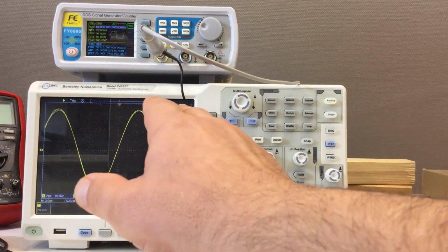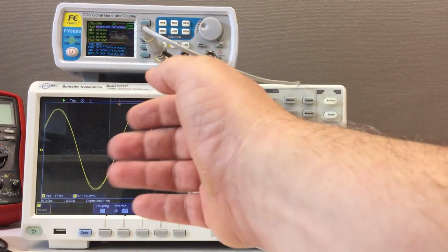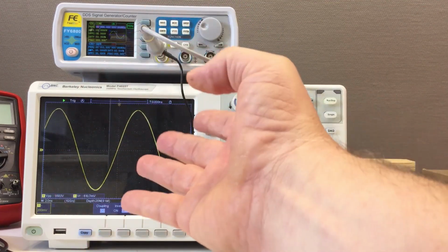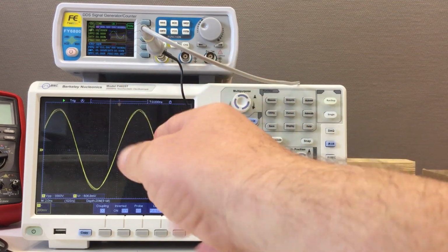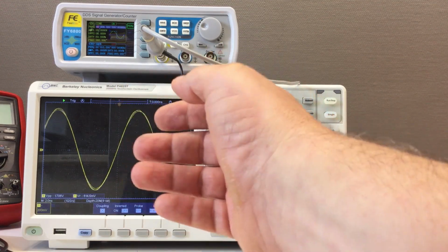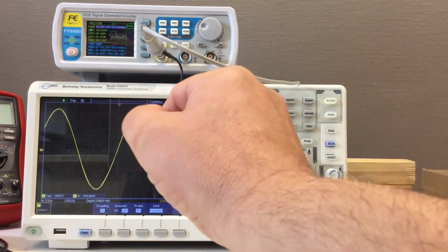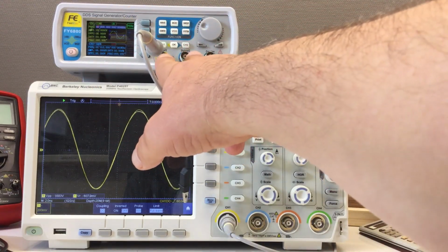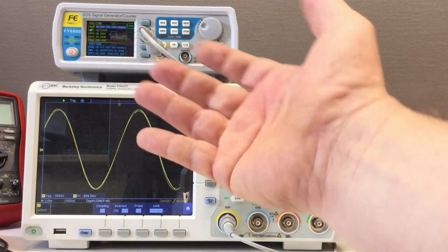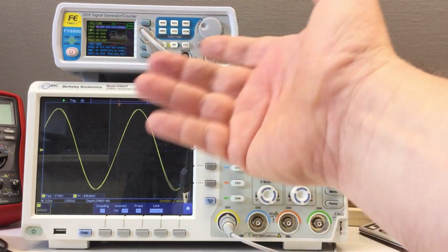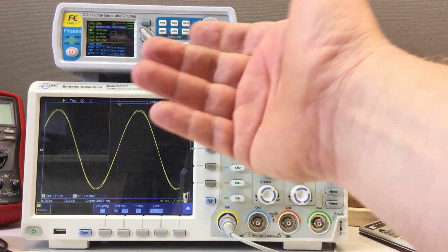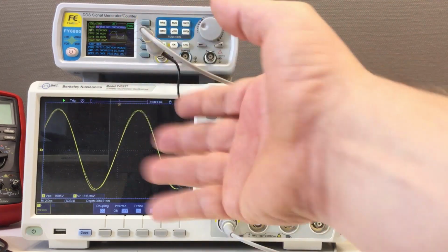A good line driver, let's say with a bandwidth of 200 megahertz and able to drive up to 100 milliamps, costs, if you buy them by the thousands, $1 or $2. You need 2 of them because you have 2 channels, and just for $2 to $4 BOM cost, plus you need some passives around them.